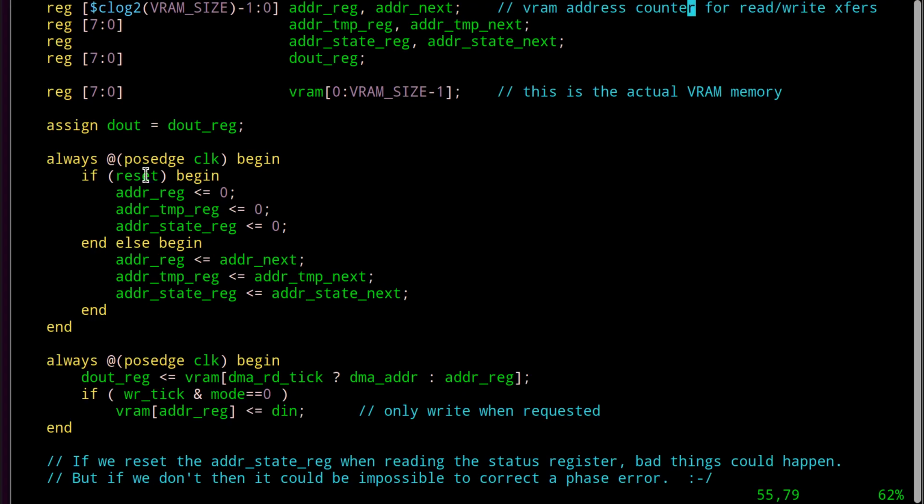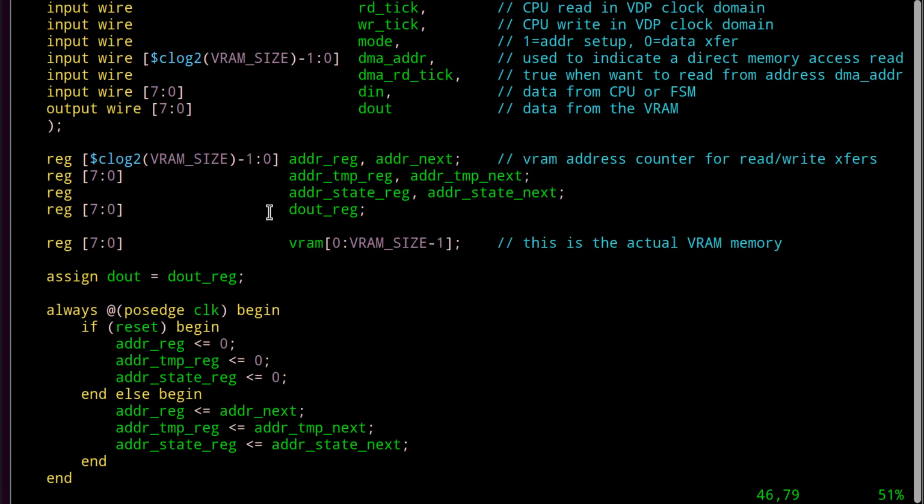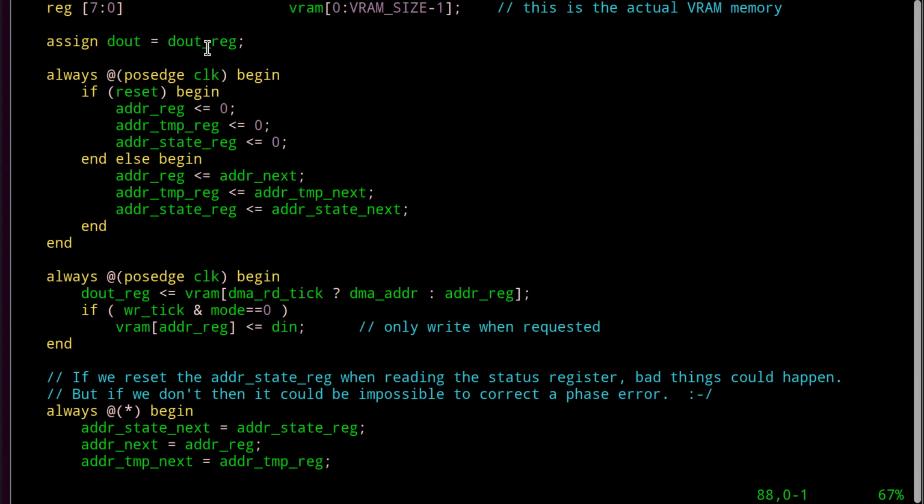Otherwise you start adding a reg in order to hold something to stage it, or put a complex expression in here that you can then not assign to a reg because you're not in an always block, and so on. I talked about this before, okay? So that's why that's simplistic and seems redundant up there.